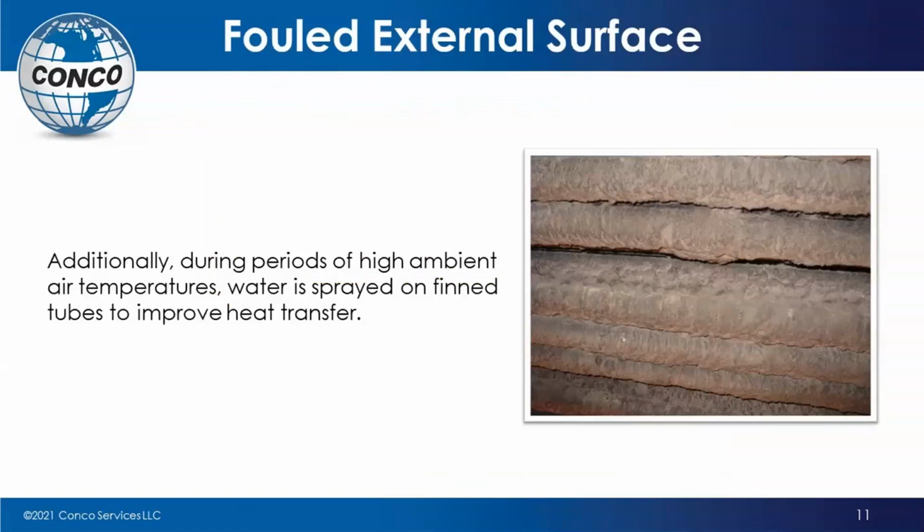So what happens? Well, in a lot of instances, the plant gets in trouble, can't bring the unit down, got to be pushing forward. So they go out and they get the water hose and they put water onto the fins themselves, which cools it down. And for that instant, it absolutely helps with their condensation.